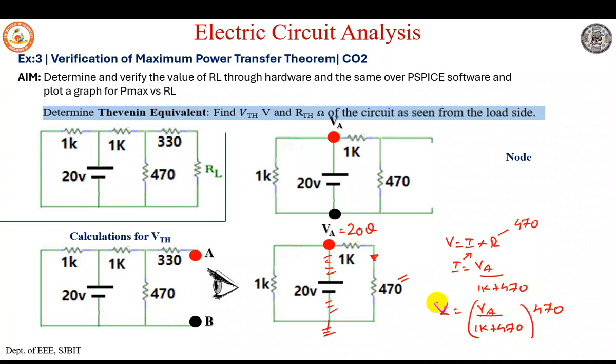So if you see, this equation is nothing but your voltage divider. If you refer, this is the voltage divider that we have applied, but the method is actually by node voltage analysis. So after solving this, you substitute 20 here, you get the same answer, that is 6.394 volts by node voltage analysis. In any theorem, they don't ask you to particularly solve by mesh, nodal or source transformation. Whichever is feasible, whichever you can do quickly, you can use that method.